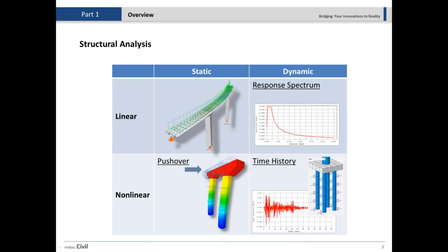This type of response spectrum analysis is satisfying for most of the bridges, even when they are located in the highly seismic zones. Depends on the size of the bridge, on the number of spans that you have, and then the depth of the site. All those are different parameters, but most of the DOTs or organizations just require you to do the response spectrum to find out the demand or dynamic demands on the structure.